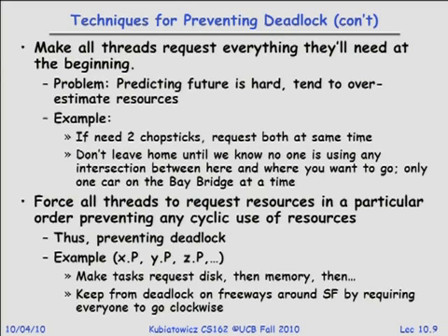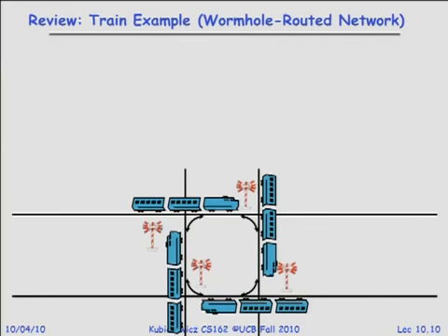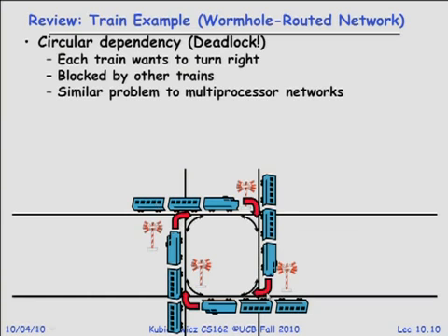So, okay. Remember, of course, that I showed you explicitly this resource allocation with wormhole routing last time, where I said networks that always go east-west before north-south don't have deadlocks, and that's exactly because we've actually eliminated this turn, and therefore if there were a cycle, it would have to have one of these turns, and therefore there's no deadlock.